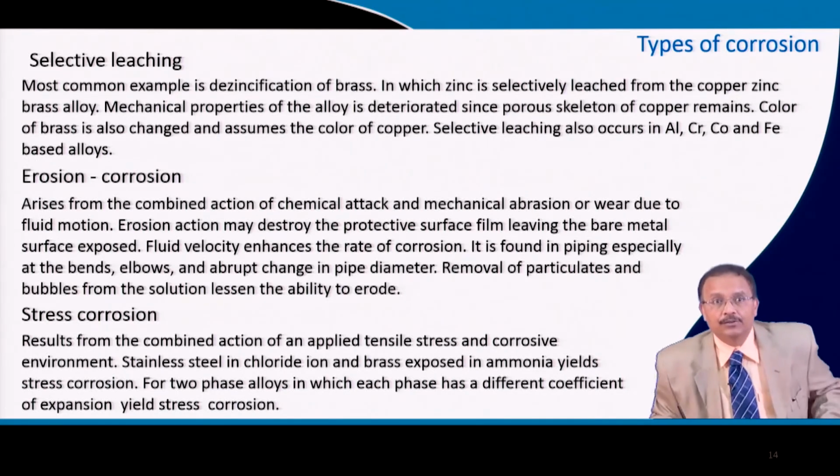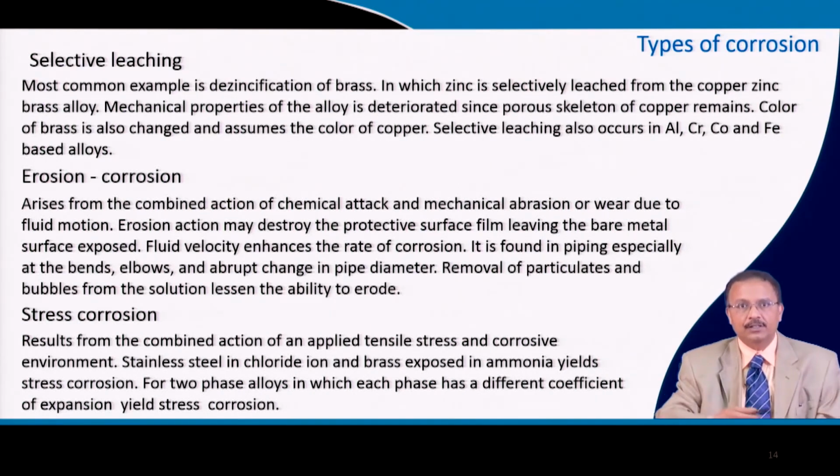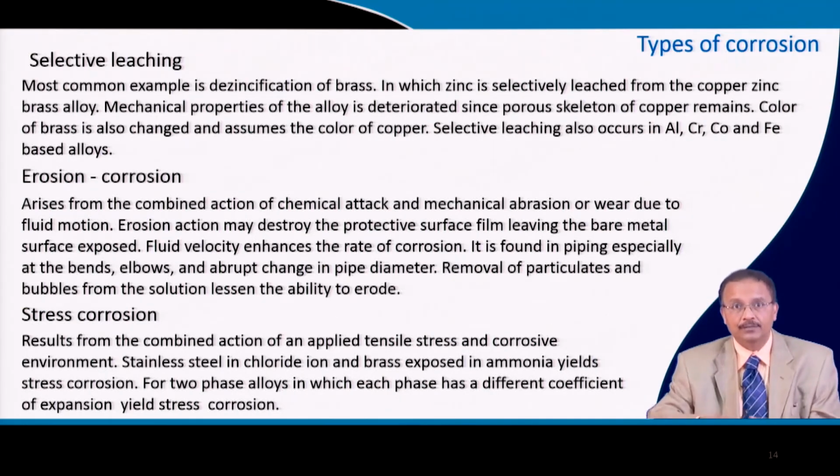Erosion corrosion I have already talked about. It arises from the combined action of chemical attack and mechanical abrasion, where due to fluid motion and erosion action, the protective surface film may be destroyed, leaving the bare metal surface exposed, and thereby the corrosive environment will corrode the metal.